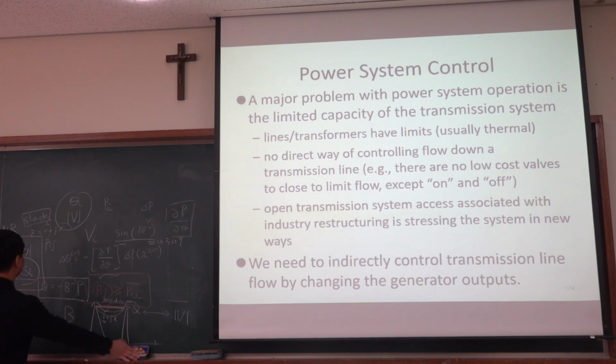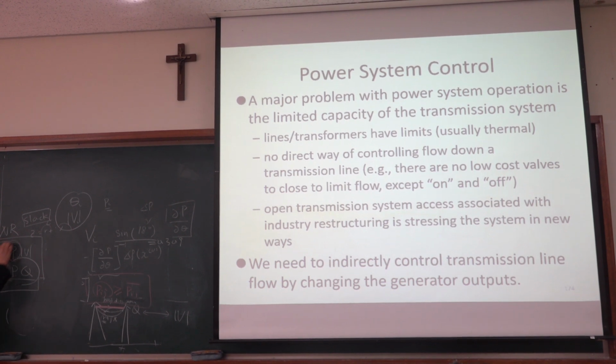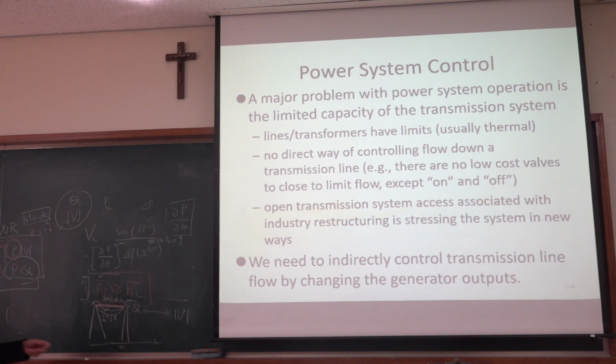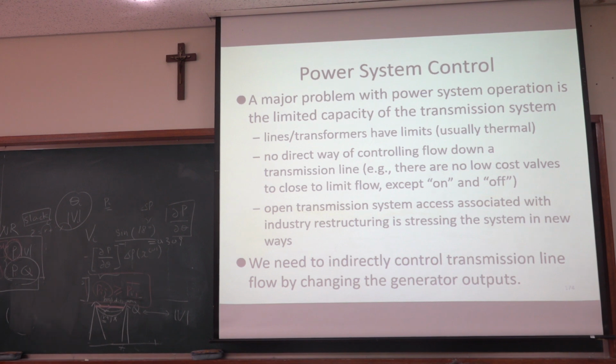Okay, interesting answer. You want to change theta? Okay. Minje? Of which one? This is a generator. This is load. Yeah, so which P do you want to change? Yeah, you can change this. You may want to change it by calling a factory manager, hey, do not consume so much active power. They can do that. That is called demand response. Okay, that is possible, but typically the operator wants to change the active power of the generator.